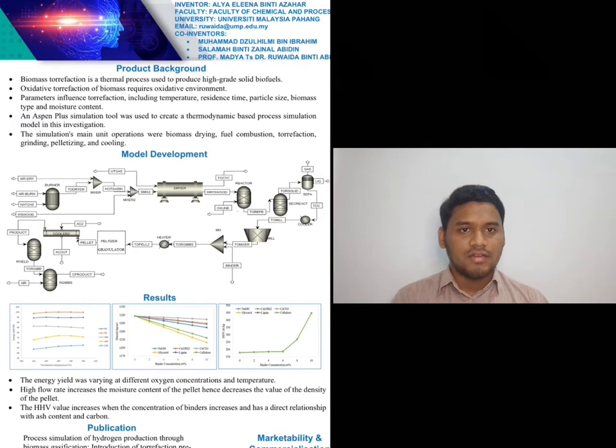EFB with high moisture content in the stream and the hot gas were mixed before flowing through the dryer. In the input section, a proper dryer dimension, the drying curve factor, and the mass transfer coefficient were defined. The raw EFB is fed to the convection rotary dryer with a moisture level between 40% to 50%. As a result, the water in the EFB evaporates and changes to the gas phase. The output gas temperature is 138.49 degrees Celsius. To produce durable pellets, the wet biomass is dried to a final moisture level of 6%.